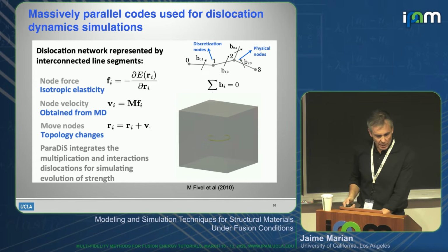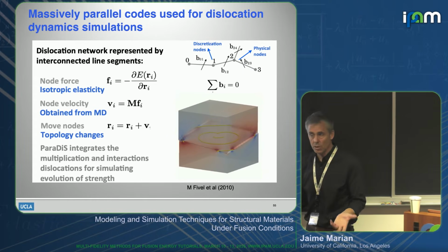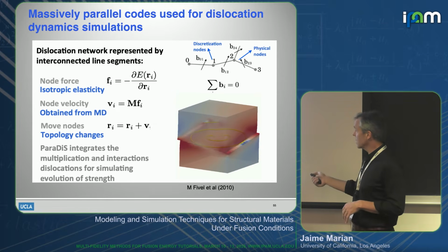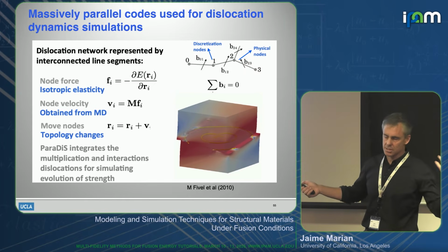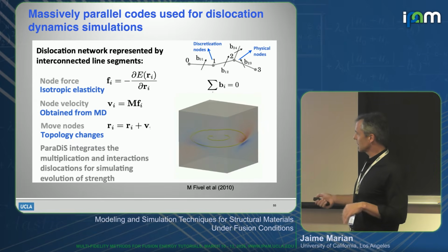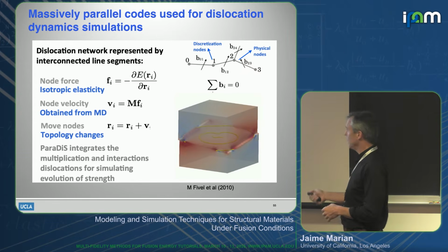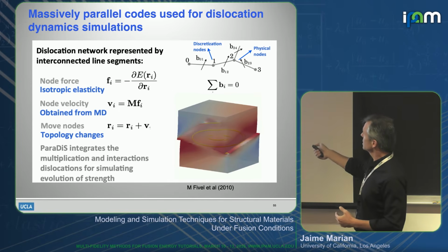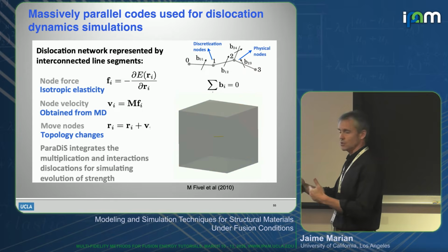And for that, we use yet another technique, which is based on elasticity theory. So now we're looking at long-range simulations, right? And elasticity theory gives you a pretty good representation of how dislocations move. Again, if you've never heard of dislocations outside the medical field, they're just line defects that control how a material plastically deforms. Okay, but we have techniques that can do that. They can piecewise discretize the dislocation lines, right? And then we use the laws of elasticity to capture their interactions.